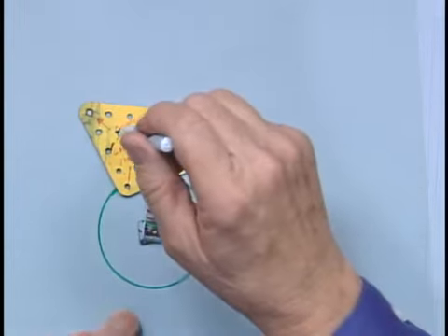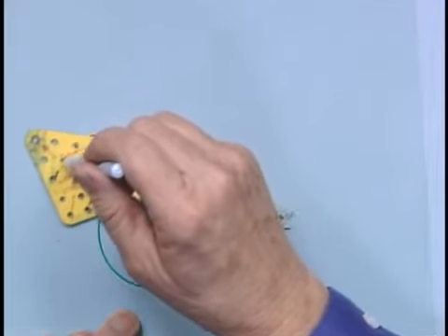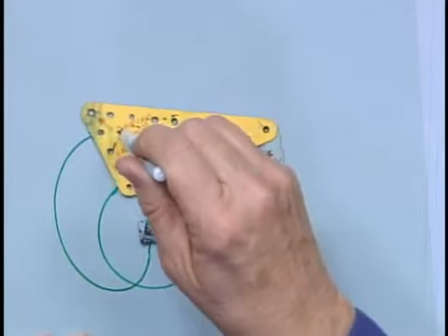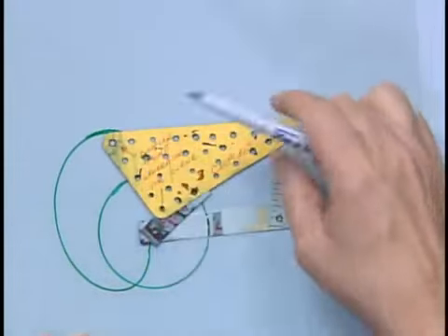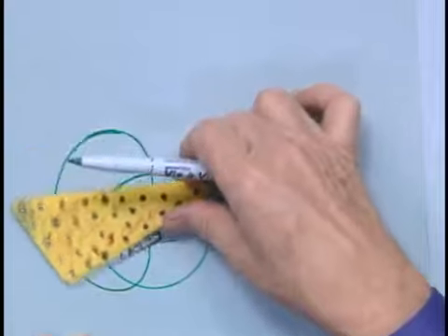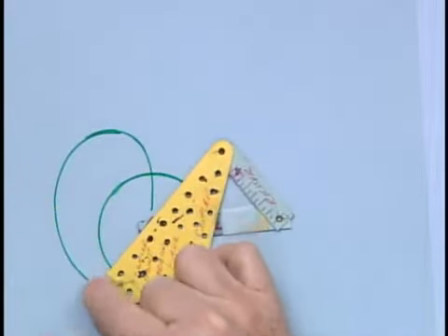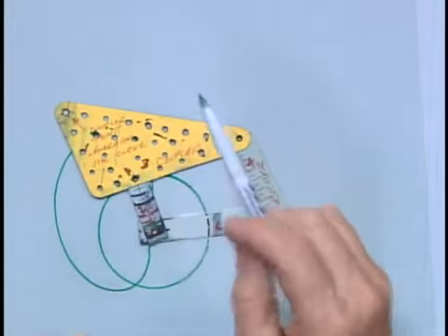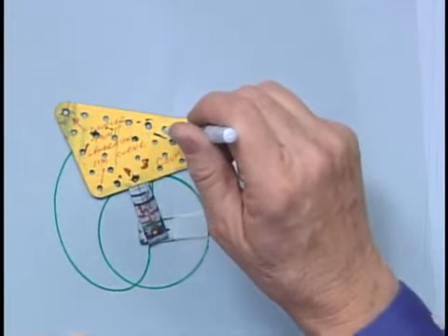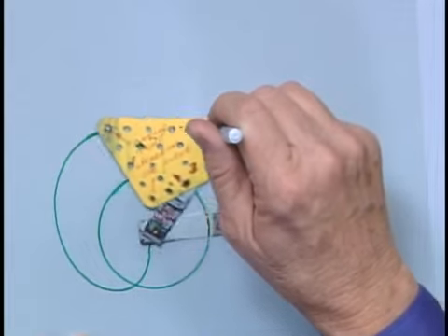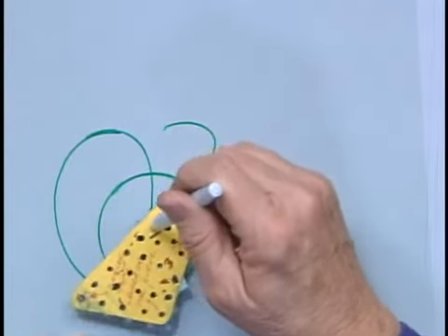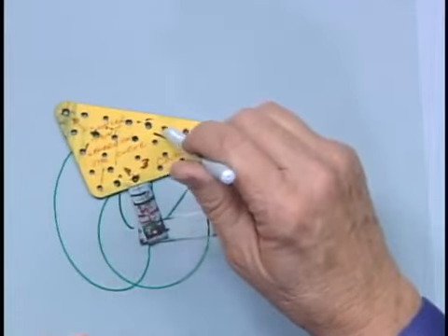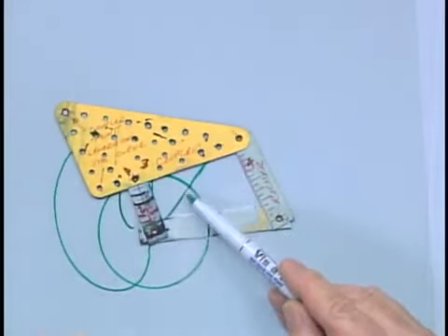However, if I take a point, say here, and I trace its curve, you can see it has a somewhat more interesting shape, sort of a flattened ellipse. It's partly hidden by my cardboard, but if I move the cardboard around, you can get a sense of it. In general, points close to instance center 2, 3 are going to be relatively uniform in shape, being somewhat elliptical. This guy over here is going to have a bit of a flat on it. It's, again, being hidden a bit by itself, but there's the flat side.